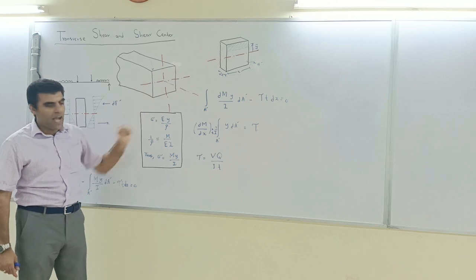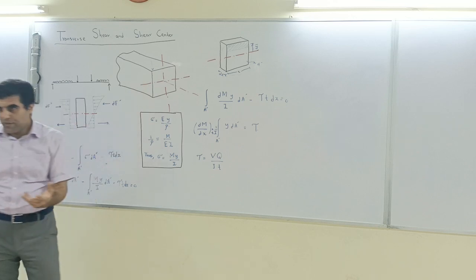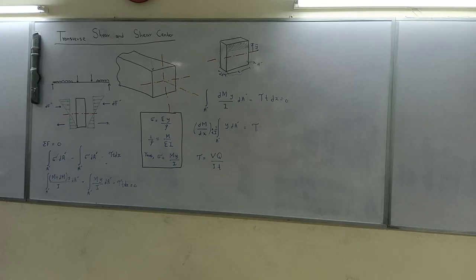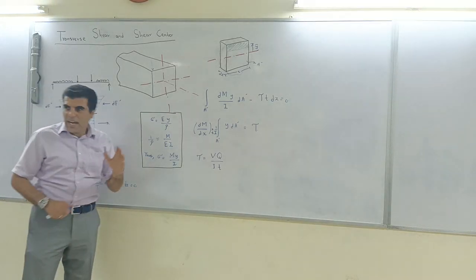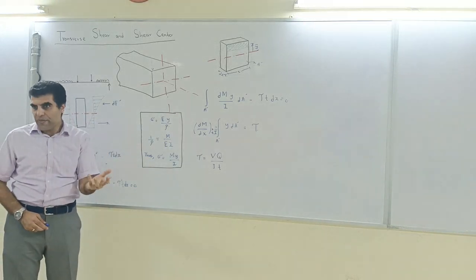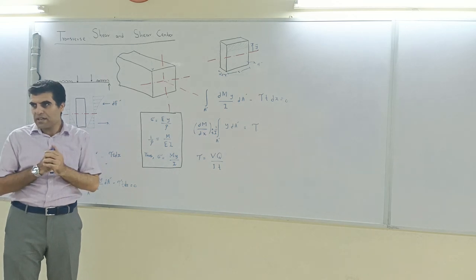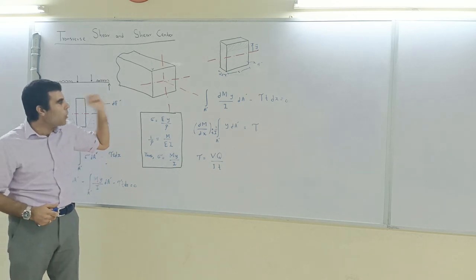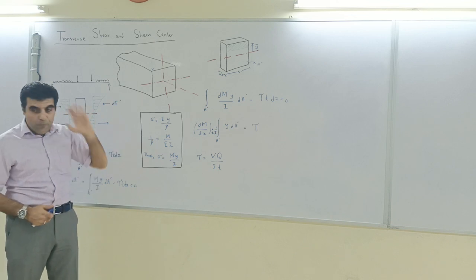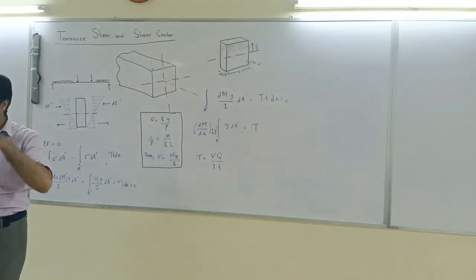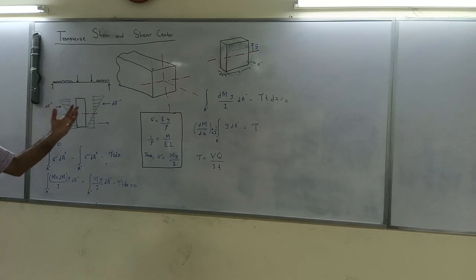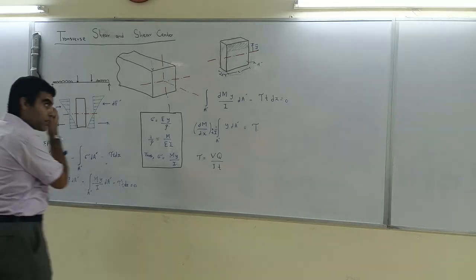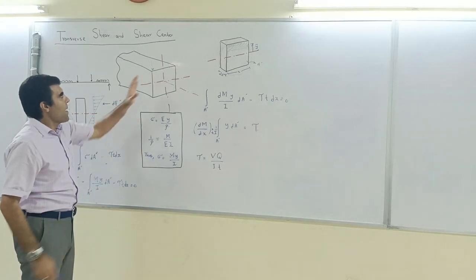However, if you have other cross sections, like channel sections, like parallel Z sections, in that case we have to work out the principal axis and then apply the load on that axis. Okay, so we have to determine the principal axis. The principal axis can't be just determined through visual analysis. You have to work it out. Okay, so that's an important factor.